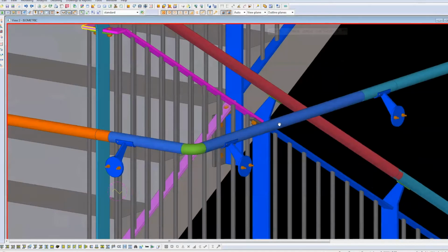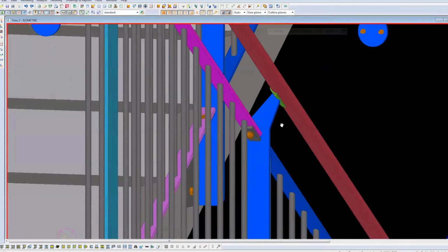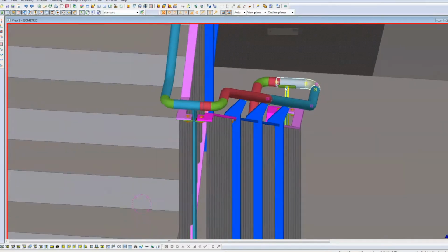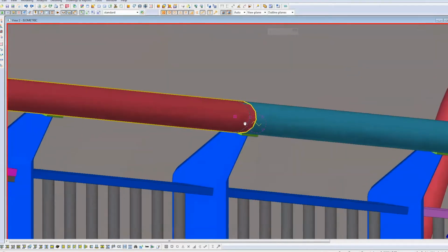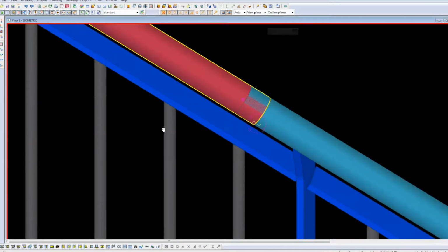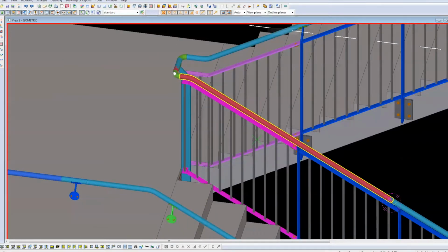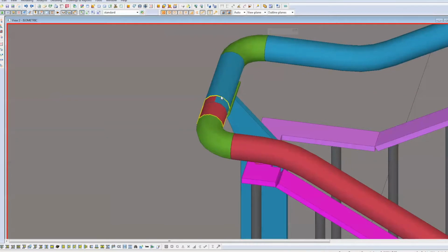All the balustrade is fixed, it's just riveted, the handrail is riveted to the balusters, so it's just been supplied in prefabricated lengths, which are over length, and every one I've been told to make slightly over length, and they've got guys on site and they're going to fit these, cut them to suit, and weld the joints and put filler in.